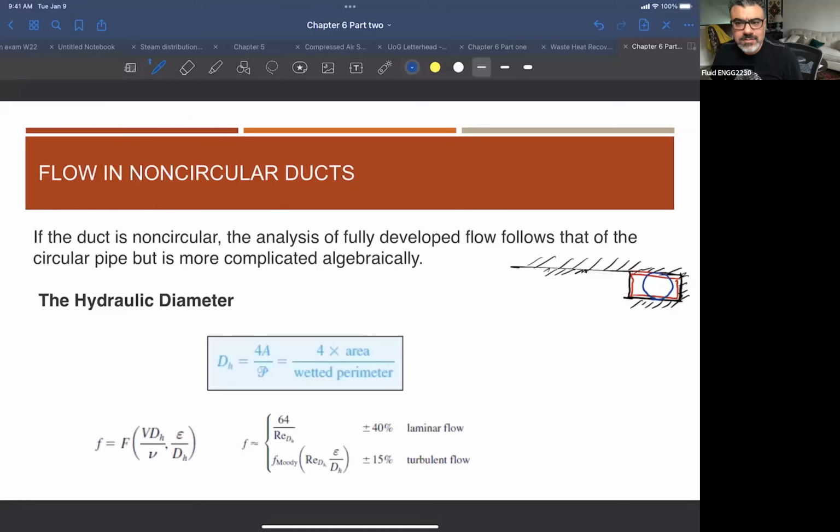Less noise. Okay. When you have a duct and you have a flow inside it, same as when you increase the speed of the fan in your car, right? You hear the noise, right? Which means that the sound of this air flowing in this duct is creating that noise, right? So most of the time for the HVAC system, you need a bigger area so the velocity is reduced. That means you are preventing additional noise inside these ducts.